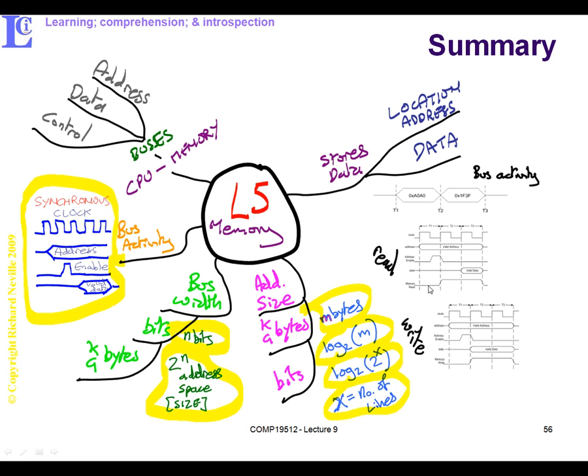Then the processor needs to tell the memory if it's either reading or writing to or from the memory, and then the third period it will actually read the valid data or write it. Okay, so that's reading and writing, take 3 clock cycles and at least 4 different steps to undertake that.